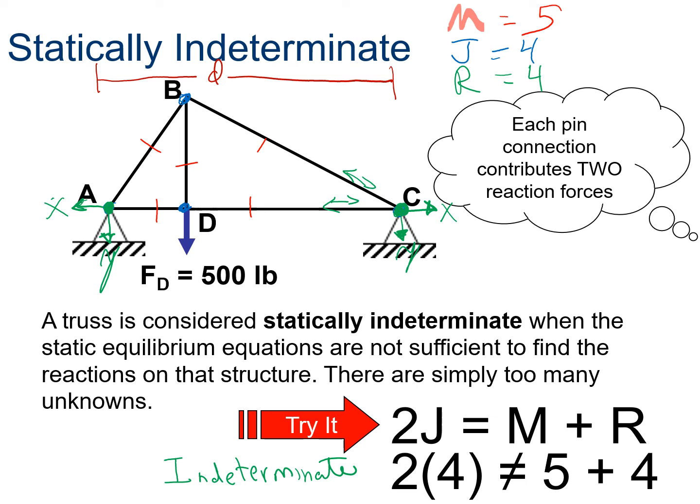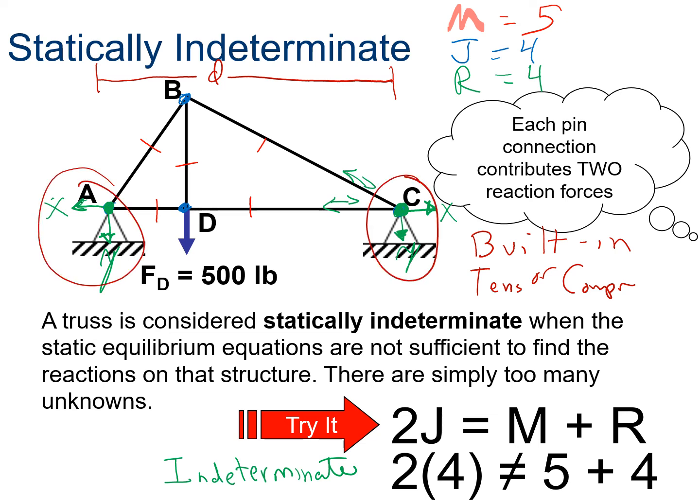So imagine you did that in the middle of summer. Because it's so hot, the metal, steel, is going to expand a little bit. And so you're going to weld it in and everything might be fine. But when the temperature churns, even just 20, 30, 40 degrees, the steel is going to contract a little bit. And now what that's going to do is preload some stresses. And so you might have some, even before anything drives on it, you might have some built-in tension or compression just because you've locked it in, because your supports are both fixed.